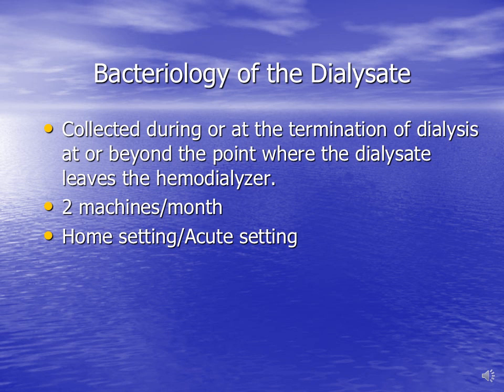One of the things is that because you have so many machines, it's not very cost effective to do every single machine each month. What you're doing is a random sampling, reflective of the results of all the machines, because what you're doing with each machine is exactly the same. You're feeding it the same water, and disinfecting it exactly the same at exactly the same frequency.